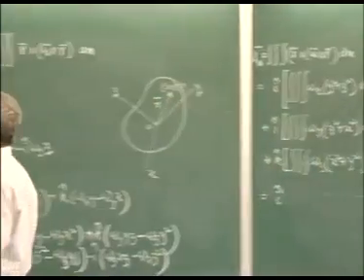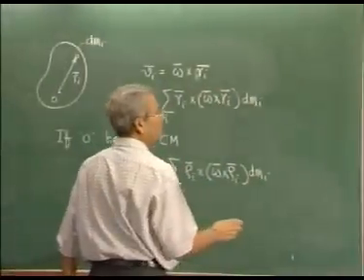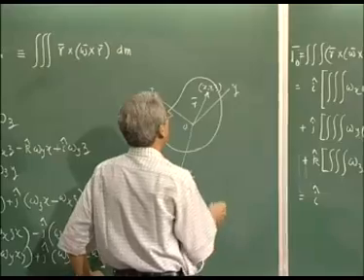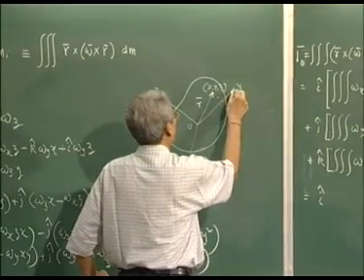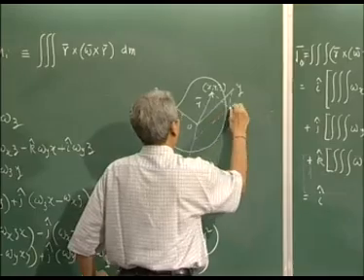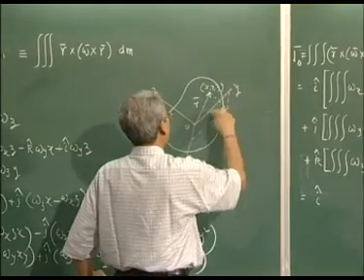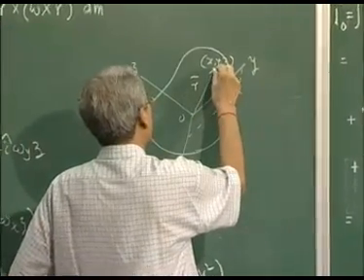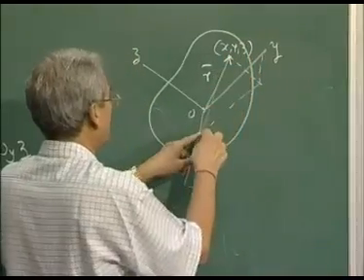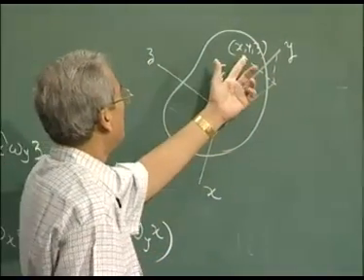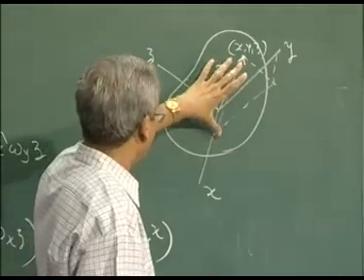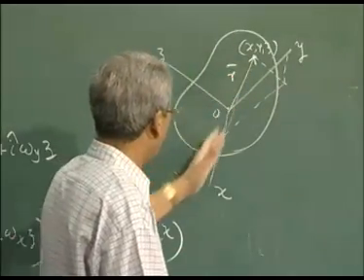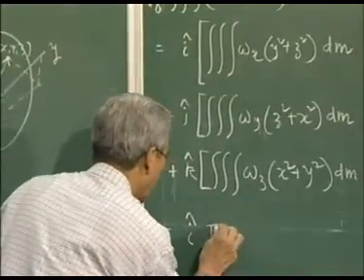You all know that if the particle is here, then y squared plus z squared, this is y and this is z, is nothing but the square of the perpendicular distance of this point about x. So, mass of this particle into distance squared from x, if you sum it over, is nothing but the moment of inertia of the rigid body about the x axis, and we denote it by Ixx.